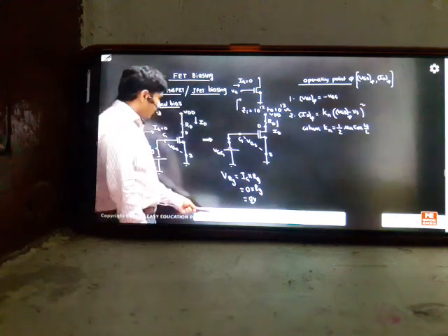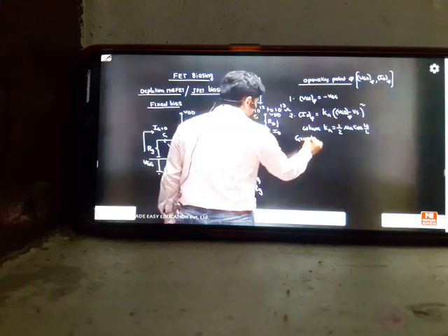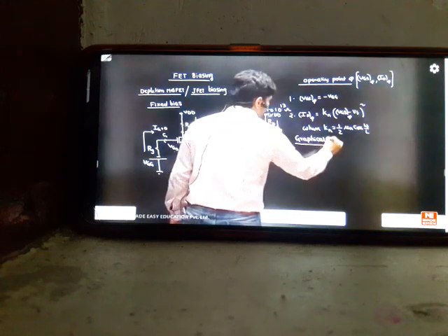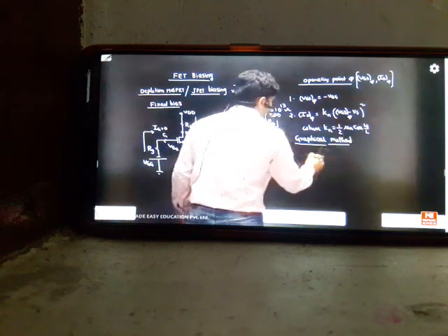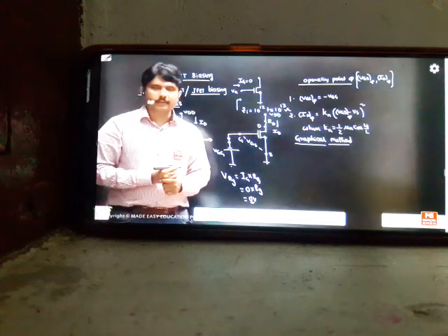Okay, so these are your operating current and voltage. But in MOSFET class, not only in this manner, we sometimes try to use a graphical approach also, because mathematics is somewhat tough here. So graphical approach or graphical method to find out the operating point. We'll see both approaches today. Circuit wise we'll calculate, and graphically also we'll understand. So this is called the load line concept we'll apply.